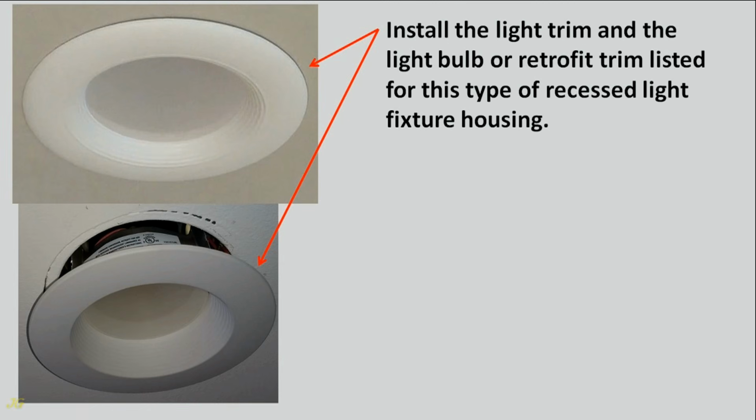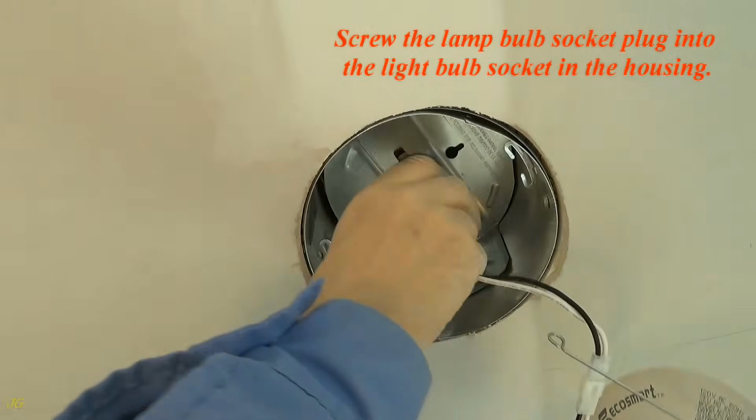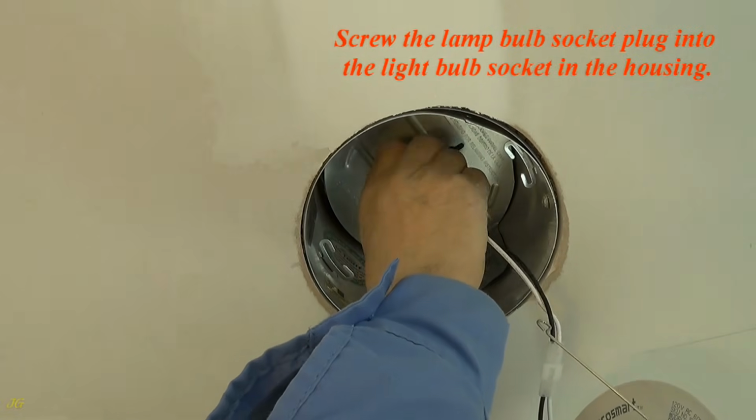Install the light trim and the light bulb or retrofit trim listed for this type of recessed light fixture housing. Screw the lamp bulb socket plug into the light bulb socket in the housing.